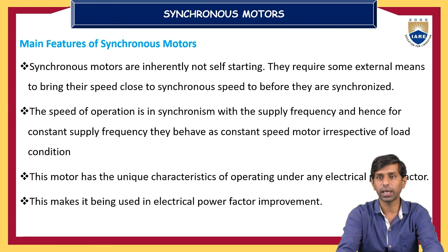This motor has a unique characteristic: it can operate under any electrical power factor. That is, we can use the synchronous motor as a synchronous condenser, under over-excitation, no-load condition. The synchronous motor can act as a synchronous condenser to improve the power factor of your existing system.